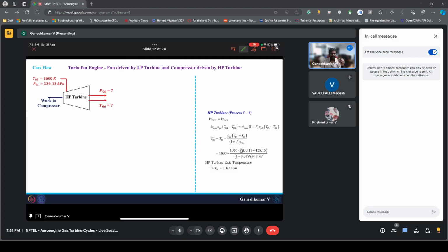Because in our configuration one, a high pressure turbine drives only the high pressure compressor. Now, it's not just that case. The high pressure turbine drives the whole compressor. In the previous case, the high pressure compressor had a pressure ratio of 12. Here, the compressor has a pressure ratio of 12 times 2.47, which is 29.43, as we just saw in the compressor section. So this change will lead to different exit temperatures and pressures than whatever we saw in configuration one.